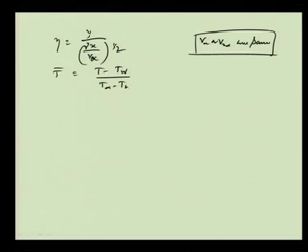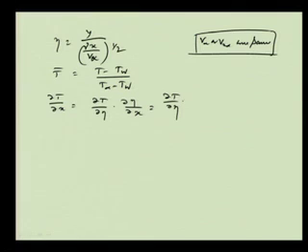Now, from there we can write that ∂T/∂x is equal to ∂T/∂eta into ∂eta/∂x, and that is equal to ∂T/∂eta into y into (V infinity by nu) whole to the power half into minus half x to the power minus 3 by 2. So, this can be exercised, this can be done.